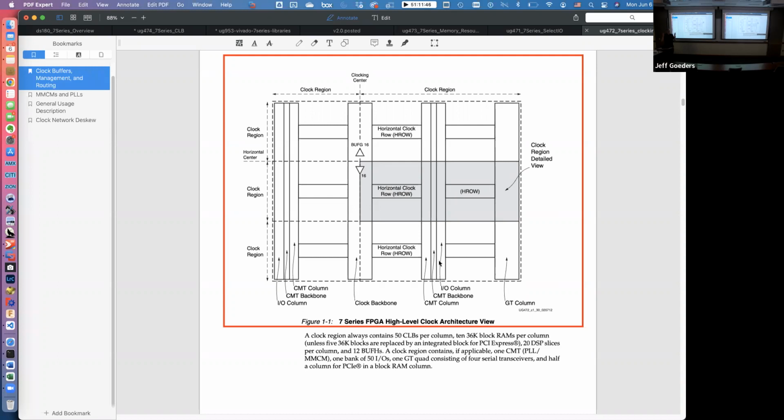Because if you have 2 flip-flops and one of them sees the clock edge half a nanosecond before the other, can you see how that might cause problems? What if the output of this flip-flop goes to the second flip-flop and the second flip-flop gets the clock late? Might he load the wrong value? He might. Or what if the roles were reversed? The second flip-flop gets the clock early before this guy. Well, now he gets the clock, but his input he's supposed to act on doesn't arrive until late. So this idea of the flip-flops all being clocked at the same time is crucial.